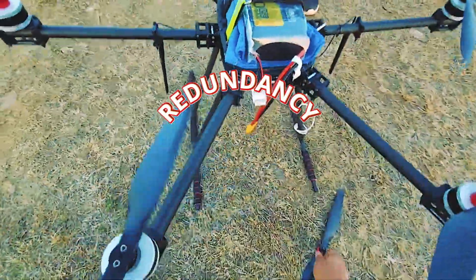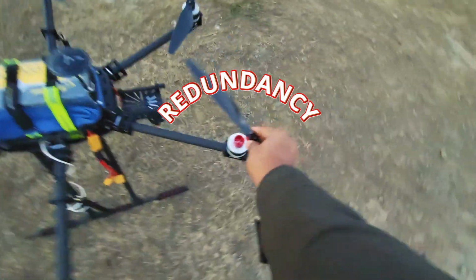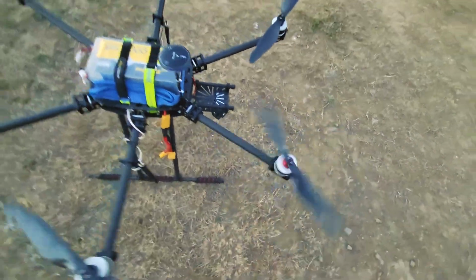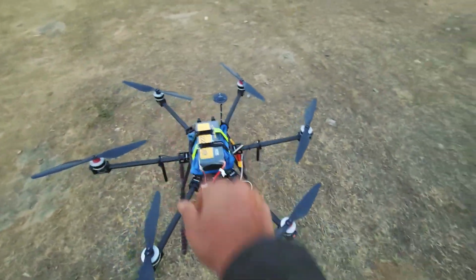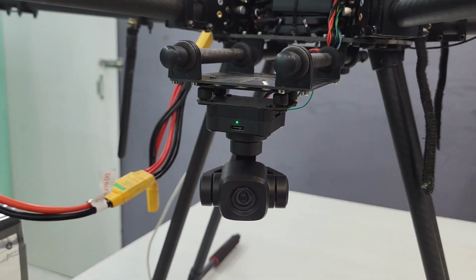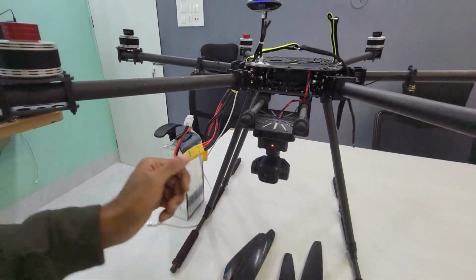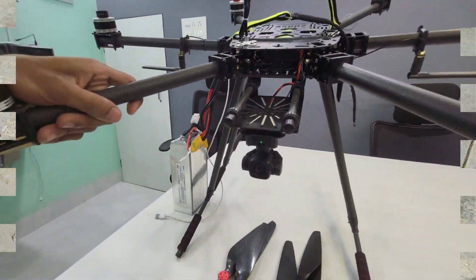Here's the thing that's really important. Redundancy. If you lose one motor on a quadcopter, you're crashing. It's just physics. 3 motors can't maintain balance. But a hexacopter, lose one motor and you can still fly. It's not comfortable, but it's possible. That's why they're used for professional work where reliability matters.